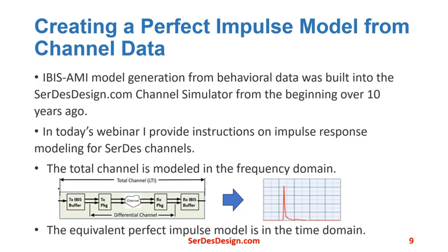Creating a perfect impulse model for a SerDes channel. IBIS-AMI model generation from behavioral data was built into the SerDesDesign.com channel simulator from the beginning. I've used this process over the past 10-plus years, providing custom IBIS-AMI models to over 40 companies based on the circuit data that they provided me. In today's webinar, I provide instructions on impulse response modeling for a SerDes channel.